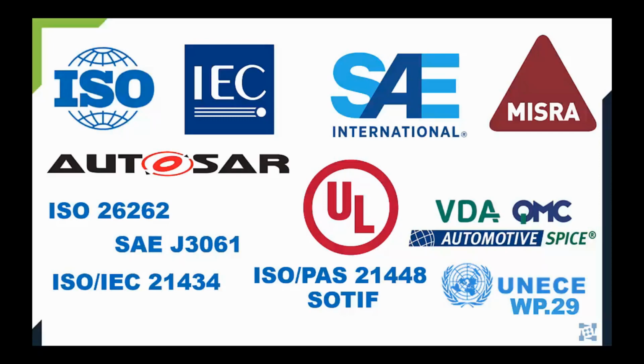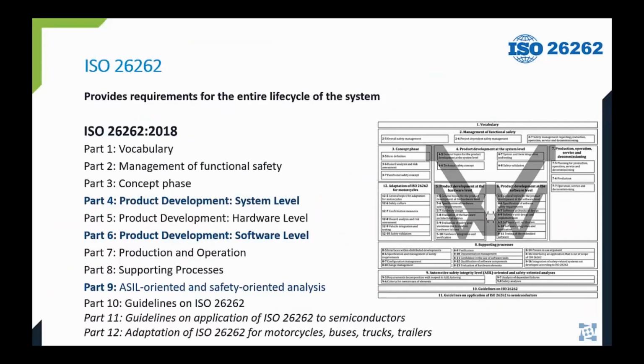All right, let's start with ISO 26262 and focus on the clauses that address software development and verification. ISO 26262 is subdivided into 12 parts, and the standard has been evolving since its first edition back in 2011. The standard's core contribution is offering a process and life cycle in developing hardware and software for automotive electronic systems.